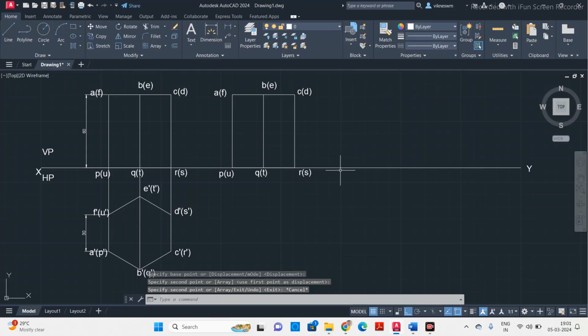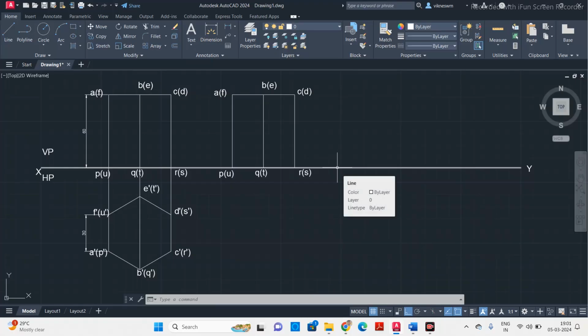So now they have given that the axis is making 40 degree. Okay, this axis is making 40 degree. So I'm going to rotate this rectangle about point R. Okay, about this point I'm going to rotate. If I'm rotating about R, the angle I should give is 180 minus this 60 degree plus minus 90 degree.